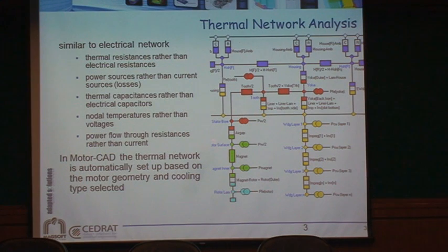We have those capacitances at the surface of the air gap. We have the insertion of energy, so that would be eddy current losses inside the magnet. There are also iron losses inside the back iron. And here we have the coils. We have 1, 2, 3, 4 layers of the coil with impregnation. That's some of the capacitance. Then we have other resistances and things like this.